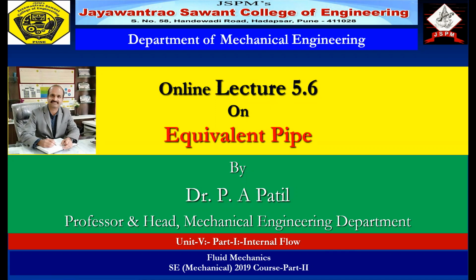A lot of labor is required for making calculations. Because if the pipeline consists of maybe 7, 8 pipes of different cross sections, then in order to calculate the head loss in each section, we have to apply the Darcy-Weisbach equation everywhere, and so a lot of labor is required. So in order to reduce that labor of making calculations, the concept of equivalent pipe is introduced. This equivalent pipe generally replaces the compound pipeline. So in this session, we are going to discuss this concept of equivalent pipeline.